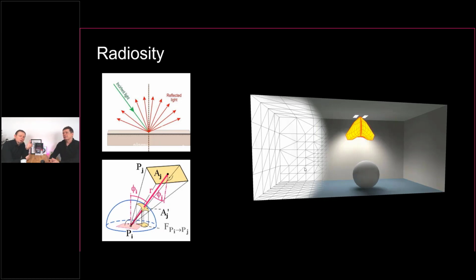Also, if you put the luminaire close to a wall, then it also makes sense to set a finer indirect grid in order to see the distribution on the wall smoothly. Also, false colors and values are affected, so everything comes down to the settings.